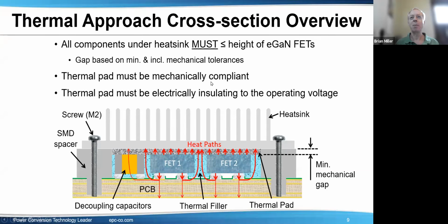And the thermal pad must be mechanically compliant. In other words, when you put on the heatsink, it'll squeeze down a little bit. And all the thermal pads have specs as far as how they work. How much squeezing relates to how much thermal resistance.